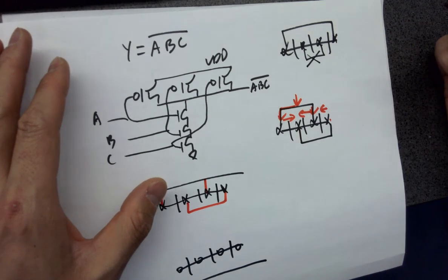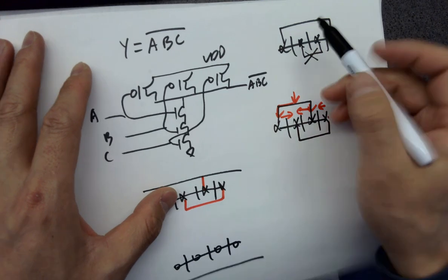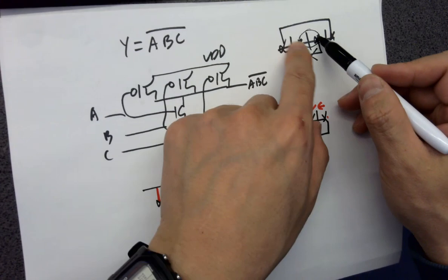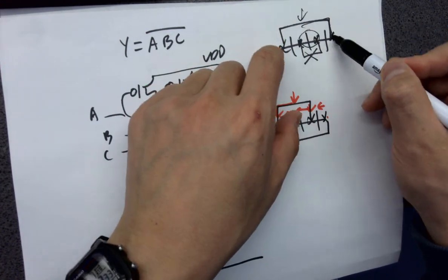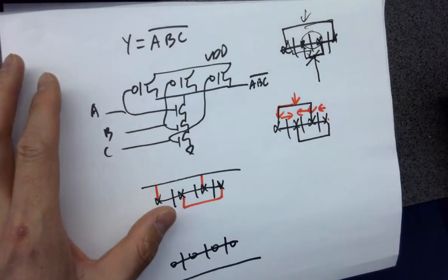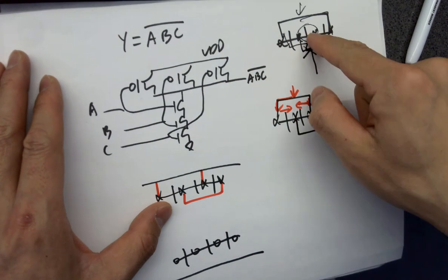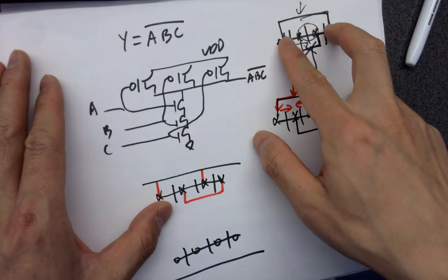So that just says A and C are in parallel? Yes. So this one is not existing anymore because it's just 1 wire. So eventually, VDD comes down here, and it's going to find a shortcut through the 2 wires and go down to the NMOSes. So this one is getting shorted. Nothing's going through this channel. It's just two transistors in parallel.